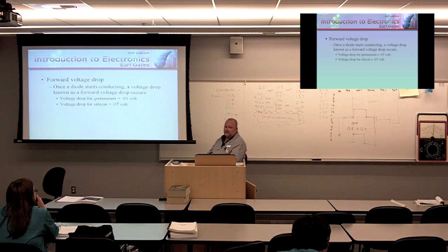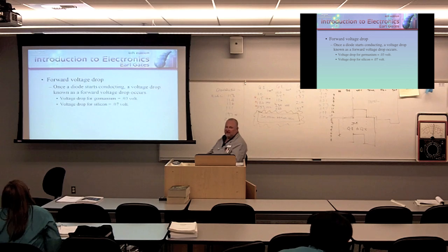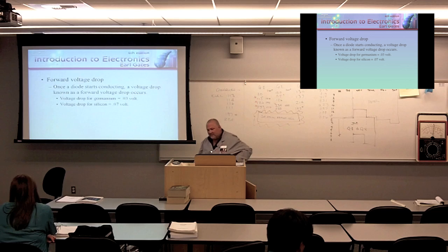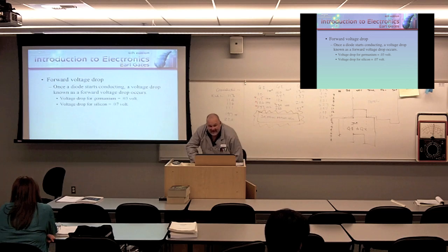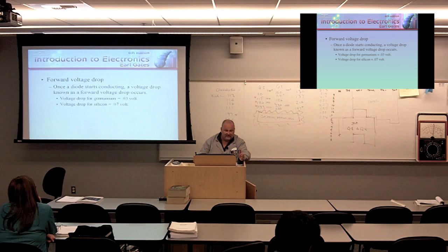It still is. That's why these components are going to get hot. Yep, and there's going to be a maximum amount of power that can be dissipated. That's a really good question. Basically, he or she who has the largest diode, physically the largest diode, wins, has the highest power.